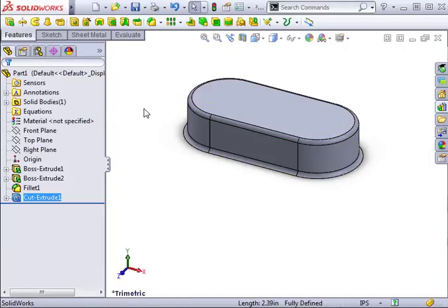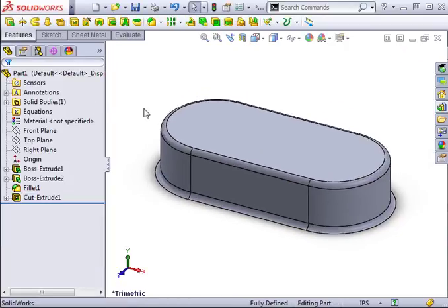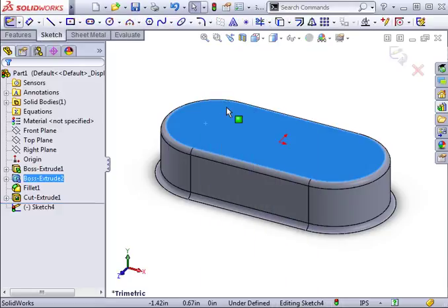In addition to stamping this shape into the sheet metal part, I also want this forming tool to create a round hole. In order to do this, I have to color a round face red. Unfortunately, I don't have a round face to color, so I'll have to create it. To create the round face, I'll have to use the split line feature. I'll start a sketch and create the shape I need, a simple circle.